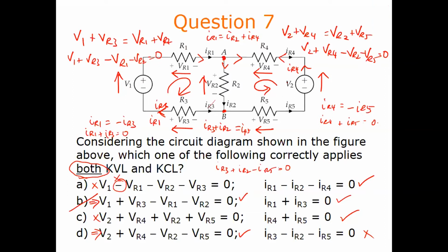So for this kind of question, when we meet these sort of circuits, whereby it's a parallel circuit, we can essentially just break the whole circuit into two closed loops, right? And solve from there. Yeah, the whole idea of breaking it into loops is so that we use the KVL and KCL laws to come up with equations, and then we solve those equations to find the unknown. All right, understand. Thank you.